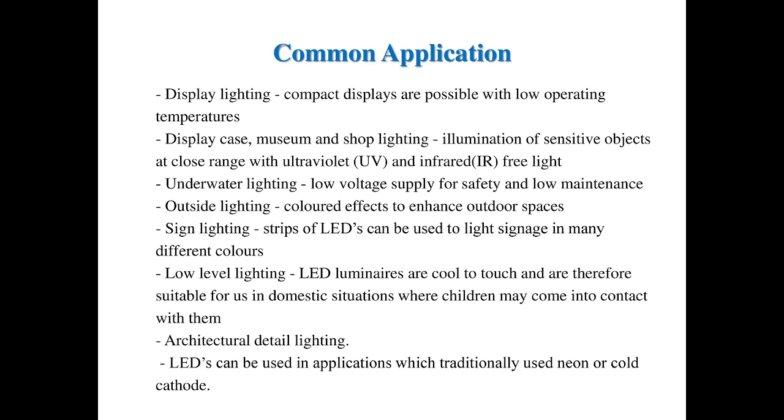Compact displays are possible with low operating temperature. Display case, museum and shop lighting, illumination of sensitive objects at close range with ultraviolet and infrared free light. Underwater lighting, low voltage supply for safety and low maintenance. Outside lighting, colored effects to enhance the outdoor spaces. Sign lighting, strips of LEDs can be used to light signage in many different colors. Low level lighting, LED luminaires are cool to touch and are therefore suitable for use in domestic situations where children may come in contact with them. Architectural detail lighting, LEDs can be used in applications which traditionally used neon and cold cathode.